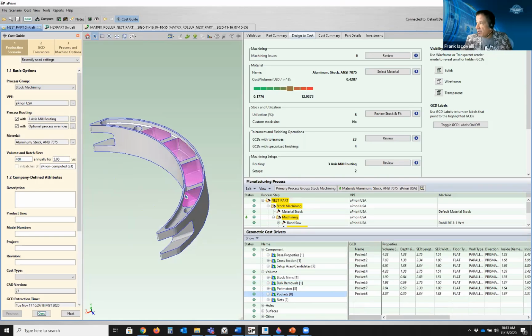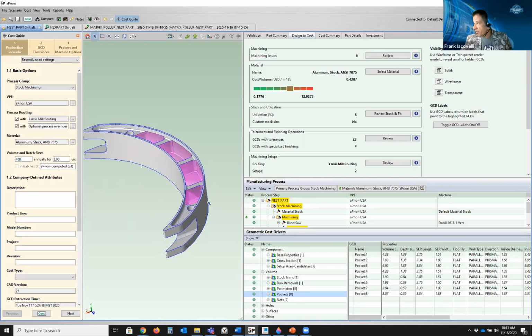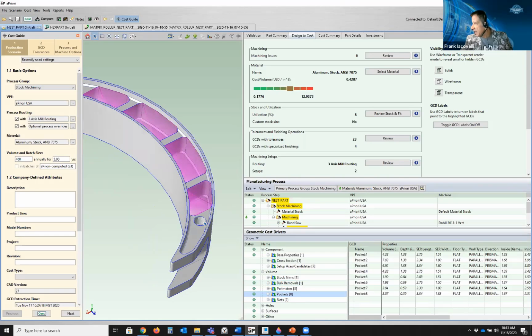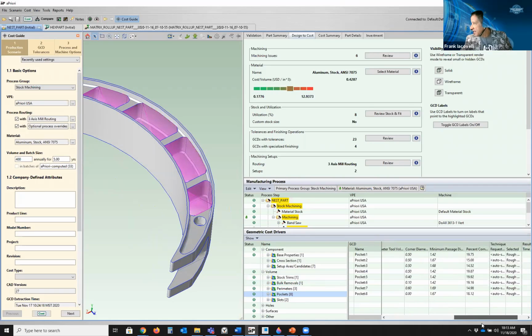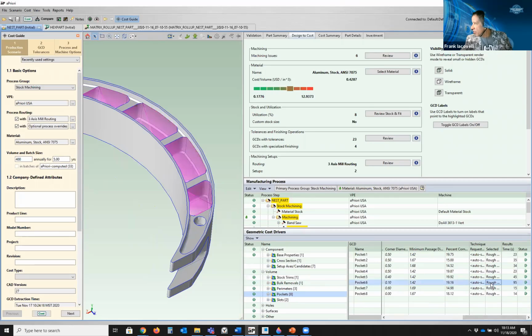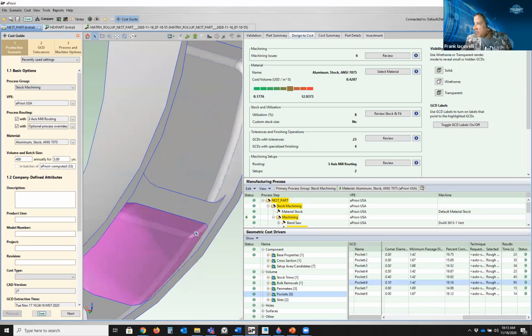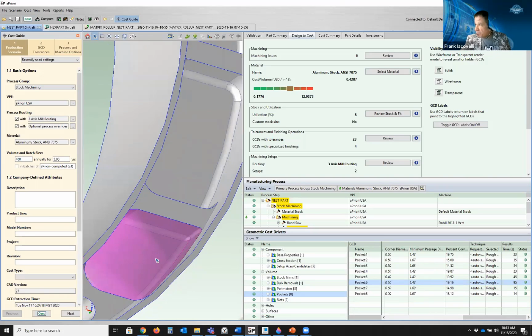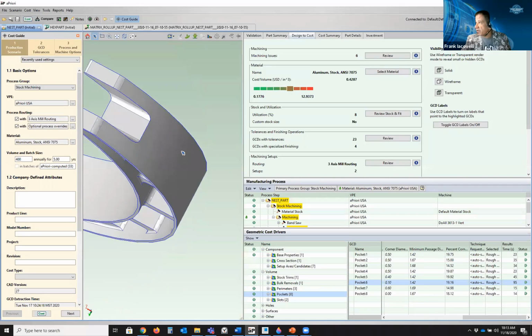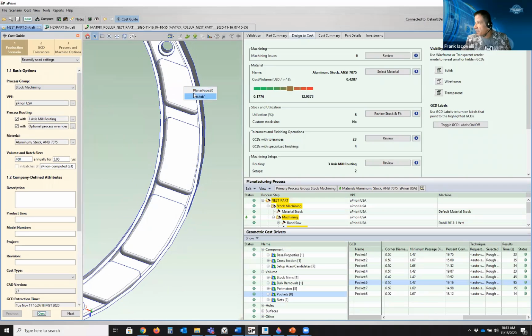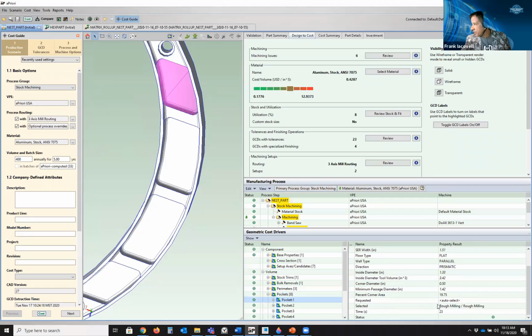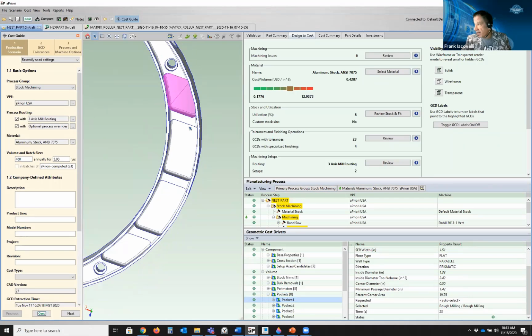And they've been around for a while, but they continue to improve. And what you can see here is different pockets, different sizes. This one you take note of, it's 95 seconds to make that pocket. If we zoom in, you can see there's a little tiny radius in the corner. So the system's smart enough to select the appropriate tools and understand that it takes longer to machine it. Versus this pocket on the same side only takes 23 seconds to make. Again, it has fatter radiuses.